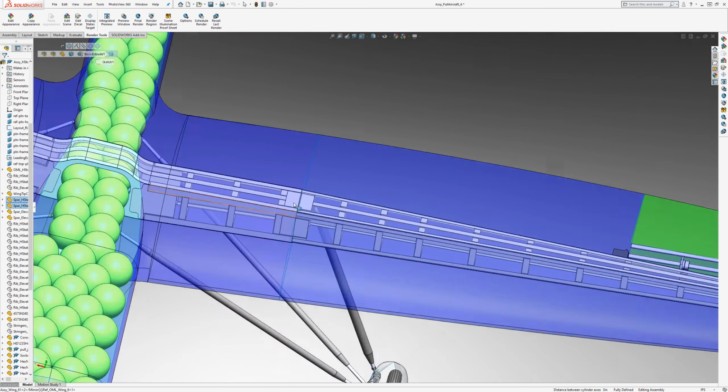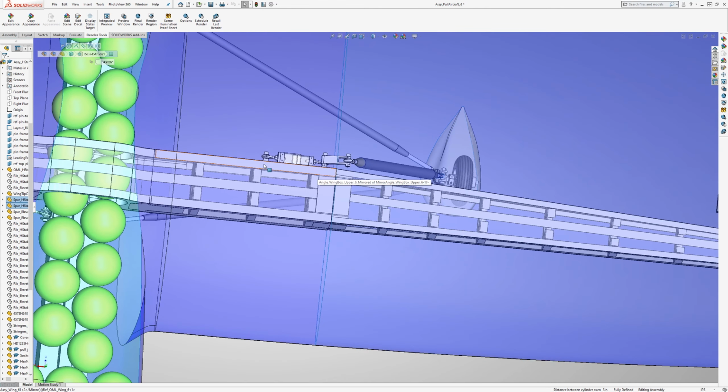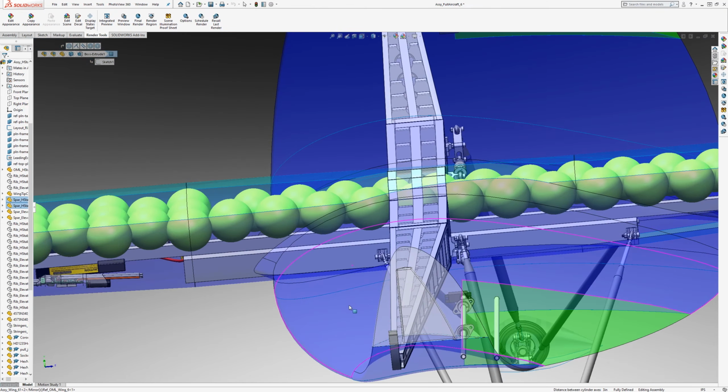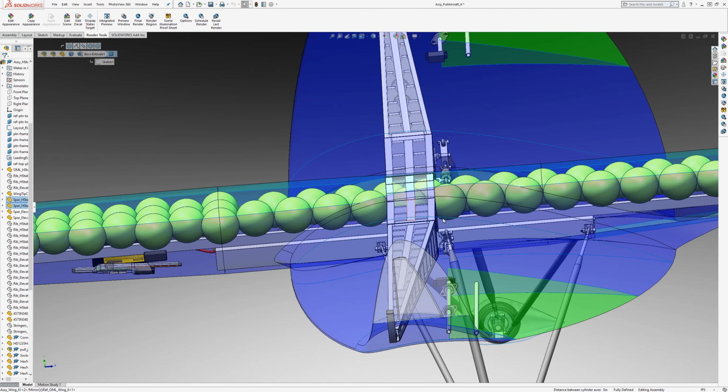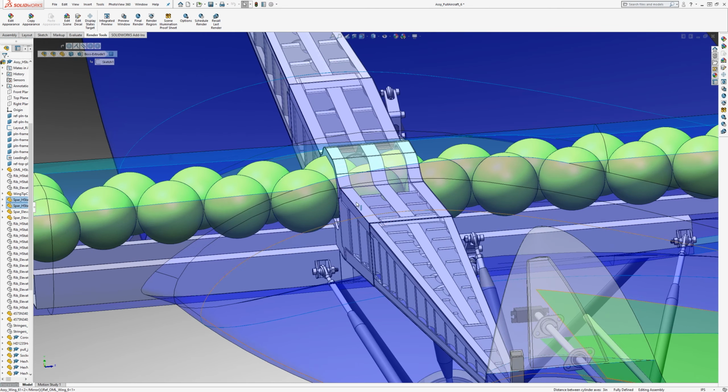Here we have the structure of the wing, and it attaches to the structure of the fuselage. If the lift of the wing is ahead of this wing box, then we would have a pitching up torsion transferred into the fuselage, and that could be done by a difference in the shears at the spars, but also by a torsion directly through the wing box.